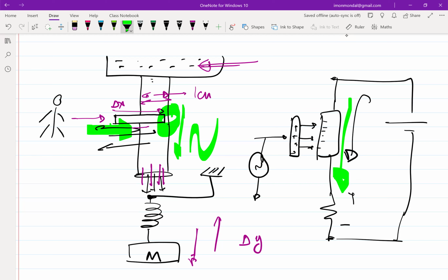Okay, but the issue is, if you use a simple metal plate, a simple metal parallel plate capacitor, if this is an ideal metal, yes, you will be able to modulate the charge, but you will never be able to deplete the metal of its charge. So if you cannot ever deplete the charge there, you will not be able to change the current that is flowing from top to bottom. You'll probably be able to change the potential on the surface of the metal plate.